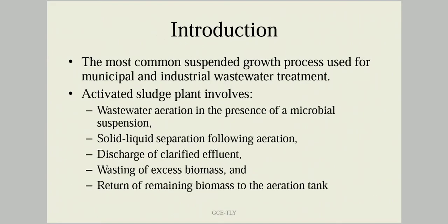The most common suspended growth process used for municipal and industrial wastewater treatment is the activated sludge process. It involves wastewater aeration in the presence of a microbial suspension, and solid-liquid separation following the aeration, then discharge of clarified effluent, then wasting of the excess biomass, and the return of the remaining biomass to the aeration tank.